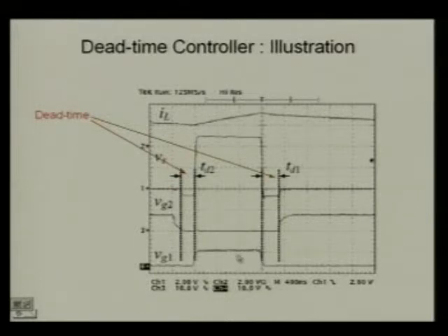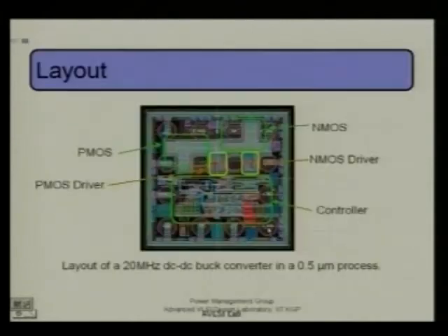You just follow the time gaps. This is 400 nanoseconds. So this will be something of the order of, I think, 15 to 20 megahertz frequency, and around 25% duty cycle. So just estimate the time. I have shown this dead time here so that you can estimate the amount of dead time that is required in contrast to the amount of on time. So this much dead time you have to provide in order to protect your circuit. This is a real design that we have shown.